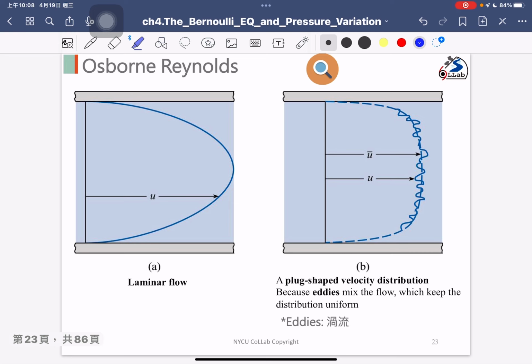So I put one velocity profile. This is the velocity profile. As you can see, the velocity is along the x directions. So this velocity profile indicates that if this is the y direction and there is the x direction, the velocity will change along the y direction. We can see that it is parabolic, right? So that's a parabolic profile we usually use to describe the laminar flow.